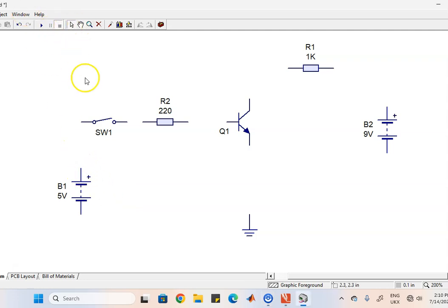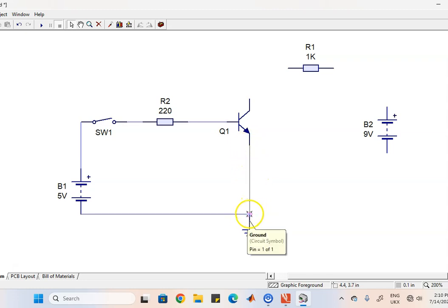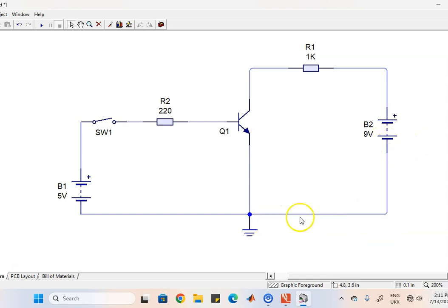With this, the base is connected in this way, like how I'm doing it, right? The voltages have already been set, so you don't need to set the values again. Then we need to connect the emitter to the ground. Then the collector side is connected to the collector resistance. Then we have the source voltage for the control. We join the negative side to the emitter. We made it clear that the negative is connected to the emitter, and the positive is connected to the collector.